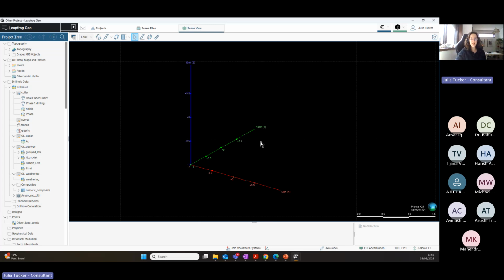Things will be a little bit displaced, and the problem will be the coordinates. And since the program is unitless, we will not be aware of what is happening. We will just see the displacement. So if you have this problem, just check in QGIS or any kind of open software whether the coordinates are in the same pattern.